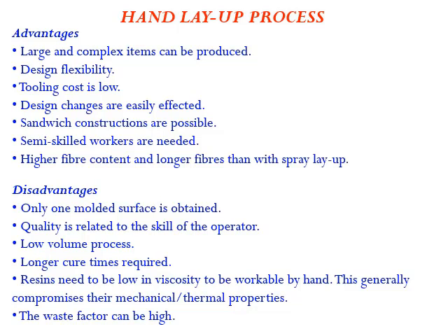Normally this process is used to manufacture boat hulls, tanks, building panels, architectural moldings. Wherever it is required to get normal application products which may not need a high strength composite material, there we go with the hand layup process. Next one will be the spray up process.